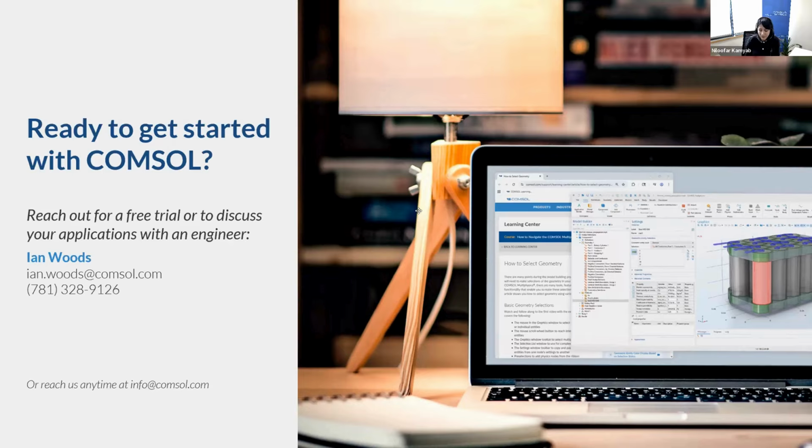And back to the other question, the computational cost: many factors go into it. It's a matter of the physics. Back to the slide that I mentioned, do you want to go with high fidelity models or simpler models in terms of theory, but also do you want to consider multiphysics? In many cases, for instance, for a lithium ion battery, 1D geometry suffices if you want to do high fidelity. But let's say your objective is tab design. You want to for sure go with a 3D geometry. All of these aspects can add to the computational cost. But one thing that I want to mention is that it's hard to estimate beforehand. It's very case dependent.